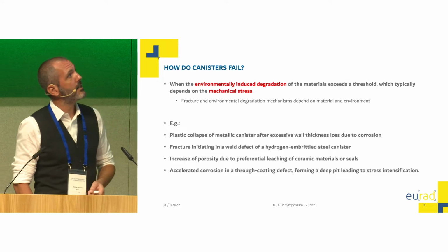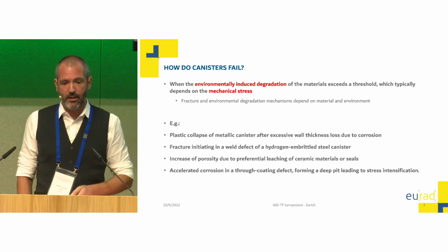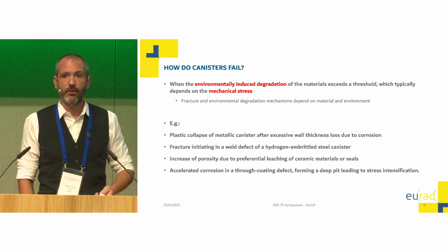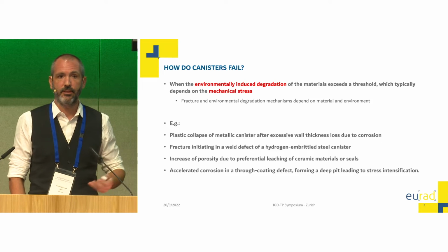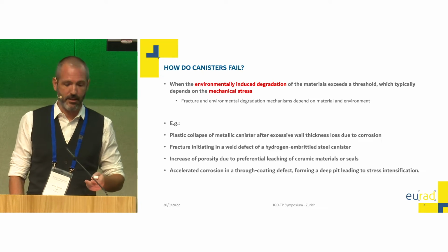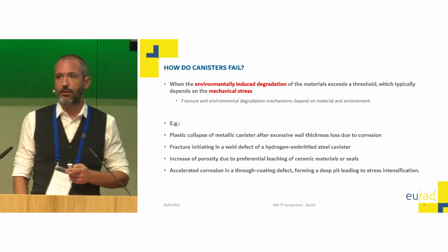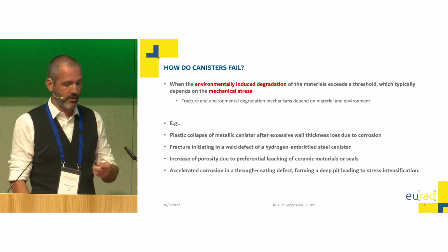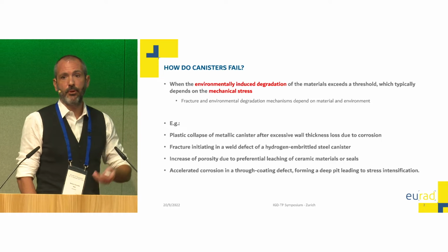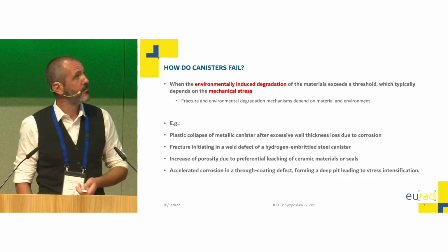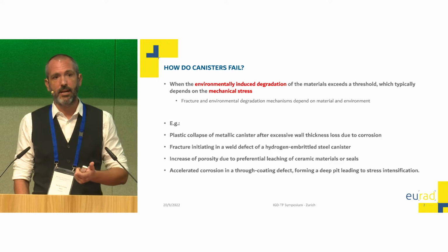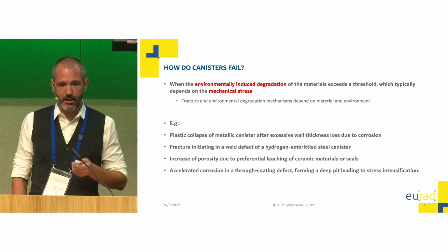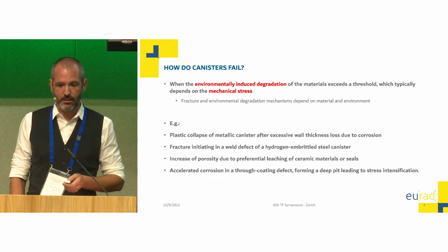Or you have a steel canister that you have welded shut, and there's a defect in the weld. In the beginning, everything is fine because the defect is small enough that it doesn't cause any fracture under the external stresses. But as the canister corrodes, hydrogen is being produced, which makes the steel more and more brittle until at a certain point you get a fracture and the thing breaks. So there's always chemistry and mechanics coming into the equation and into the process we need to understand and to predict.